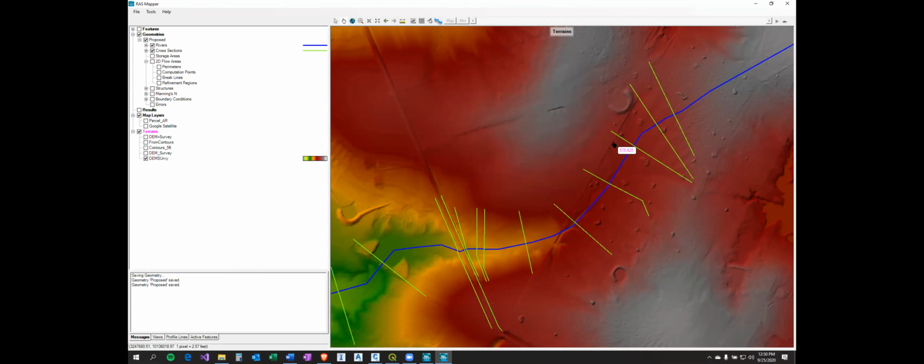I've had conversations with the guy that wrote this software. His name is Cam Ackerman. He works for HEC. There are some weird things that happen, and I want to point this out to the group. So let's say you do a floodplain delineation inside of RASMapper, and you get a DEM surface of water surface or velocity or whatever. When it exports, it'll create a DEM at the equal resolution of the underlying surface itself. So if, for example, Adam ran a hydraulic analysis on just this little reach, it would export a DEM that is gigantic. So it would be the entire surface that he's running the analysis on, which is irritating. So you'd have to do some GIS cleanup to trim it down and remove those nulls. Just a heads up, that was intended. The software was built to do that. I think it's kind of a bit of a fallacy, but it is something that I'm seeing.